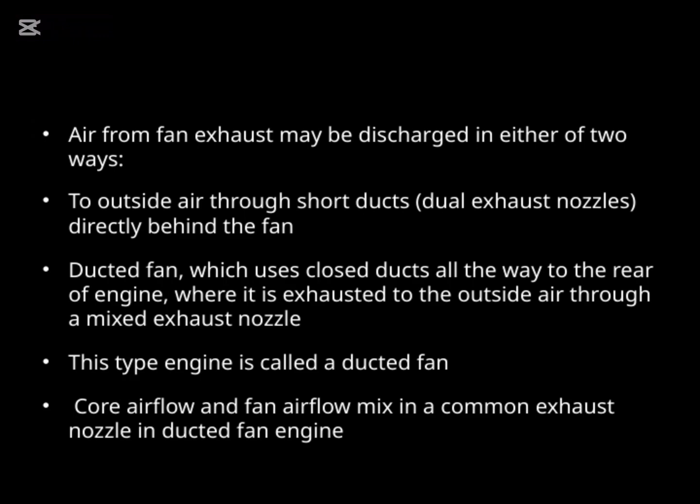An important point here is that, in a ducted fan, the core airflow, which passes through the engine core, and the fan airflow, which is generated by the fan itself, actually mix together in a common exhaust nozzle. Understanding these different exhaust methods is crucial because they directly impact engine efficiency, noise levels, and overall performance, which are key themes in our discussion of jet engine design.